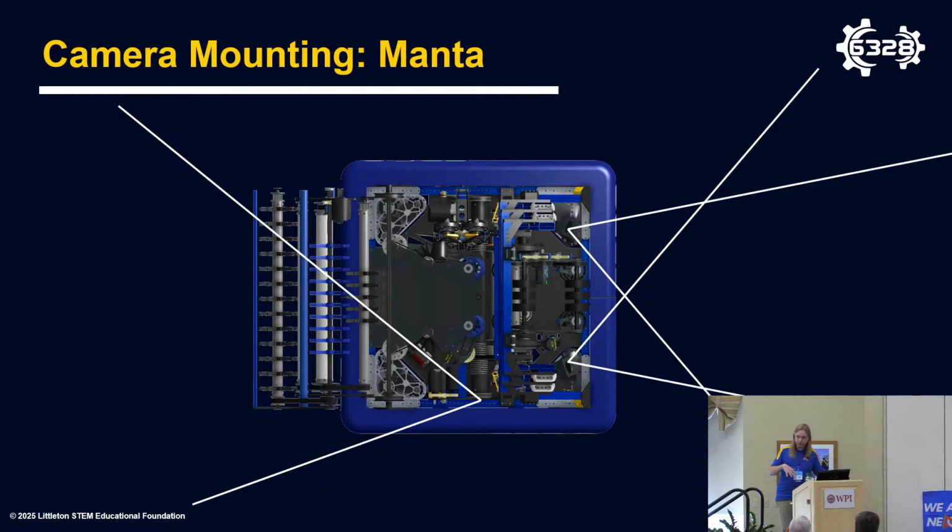Now in the back of the robot, we also had a camera. There were two variations of this robot. When we were picking up coral with a hopper, we were using that back camera for alignment to the tag on the human player station, so it was angled up quite a lot to support that. And with the ground intake, the latest iteration, we angled it down and switched it to a color camera for game piece localization. So we're switching it based on the exact needs of what we need the vision system to support.